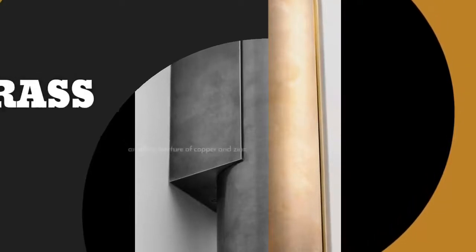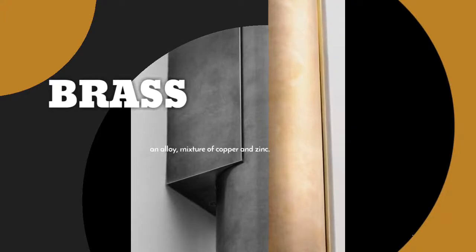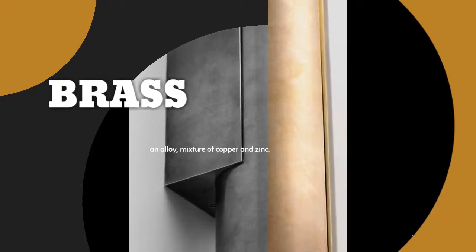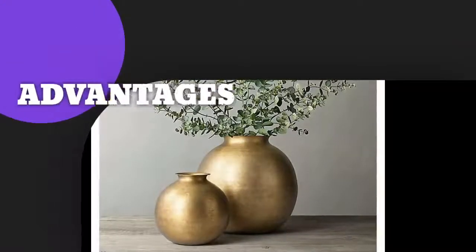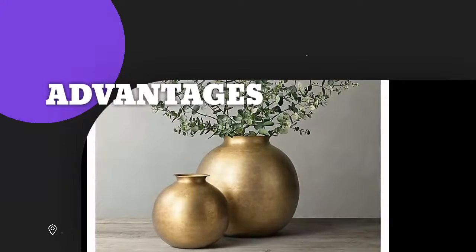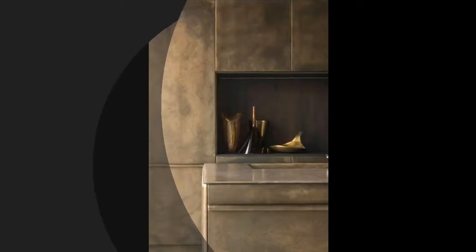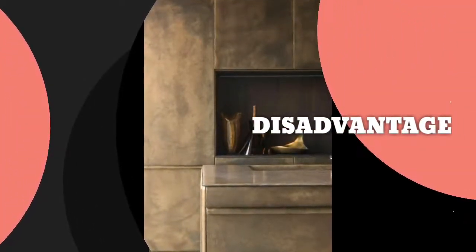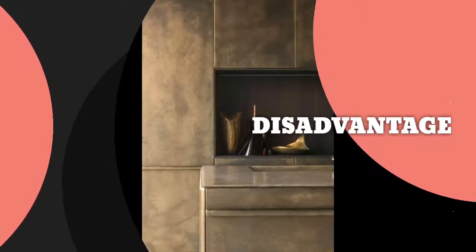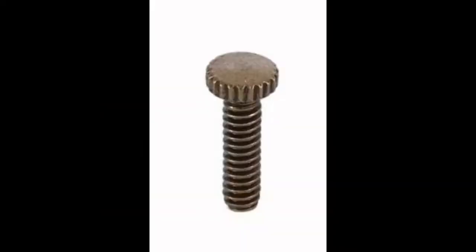So first up is brass. Brass is an alloy or mixture of copper and zinc with small quantities of other elements added to improve it. In terms of advantages, brass is superior in workability and resistance to corrosion, but its downside is that it's less hard and strong than steels. We commonly see brasses in lightweight things such as doorknobs, screws, nuts, railings, and more.